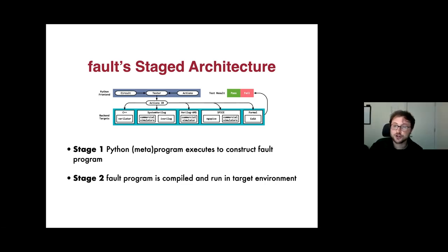Yeah, I mean, this is kind of inherent to the structure of a generator, I would claim, where you have to run that generator in order to produce the source code. There are also other major issues we've been running into in terms of symbol tracking and debugging. If you have one line in your original generator code that is executed multiple times to produce different portions of the circuit, which happens often, like a for loop stamping out a whole bunch of instances, then all those instances are going to be mapped to essentially the same line number for debugging purposes, if that makes sense.